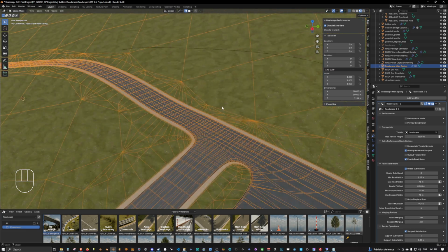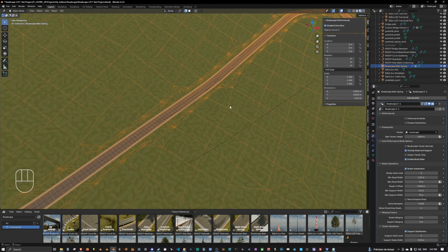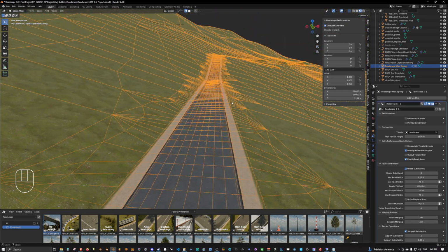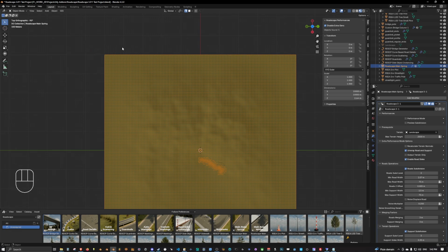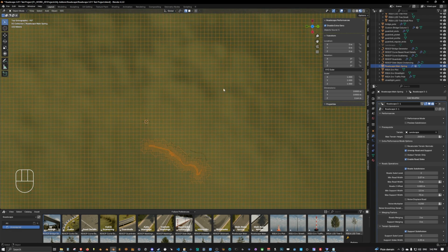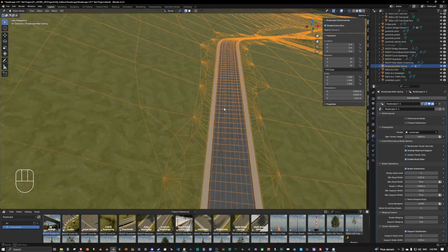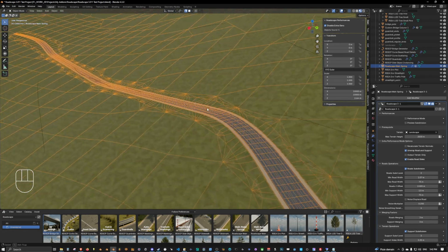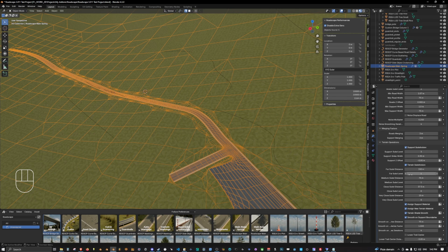So as I've just mentioned, we also have a new terrain merging. This is activated by default. You cannot go back to the old terrain merging. It has been removed. This is a 10 by 10 kilometers terrain. We can see that these are big faces. This is a very low poly terrain. And as you can see, there is no problem in merging the terrain with the support whatsoever, with a very low terrain subdivision factor activated. In fact, we only have far subdivision level to 1 and medium subdivision level to 1 as well activated.